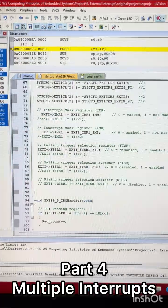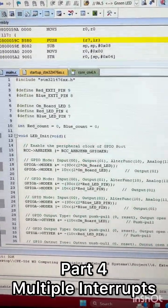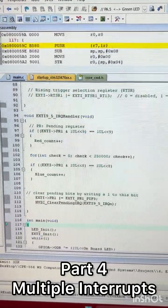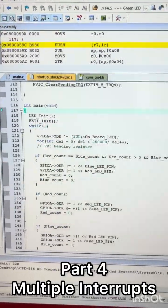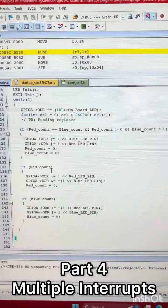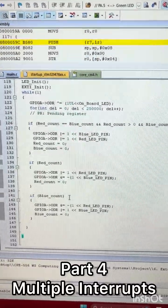Part 4, multiple interrupts. I have two buttons and two LEDs. Each of the buttons is connected to the same IRQ. Here I have taken a red and a blue counter, which will get triggered when the buttons are pressed. Once it goes into the main code, it will decide if the red button is pressed even once, then it will turn on the red LED and turn off the blue, and vice versa for the blue.